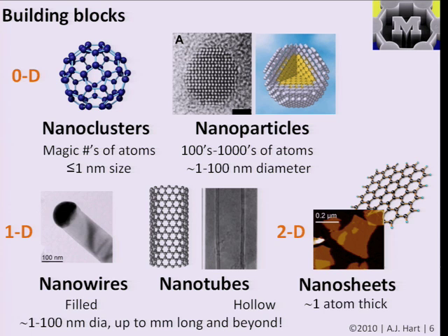Things like chemical vapor deposition or evaporation, with particular attention to the fundamental processes that happen. And there are, in fact, a lot of similarities from growth of bulk crystals to growth of nanoscale crystals, but now by examining the relationships between, say, how the nanowire grows and what its properties are, or how the atoms are incorporated at the interface here, is letting us really understand the fundamental mechanisms by which these structures are produced.